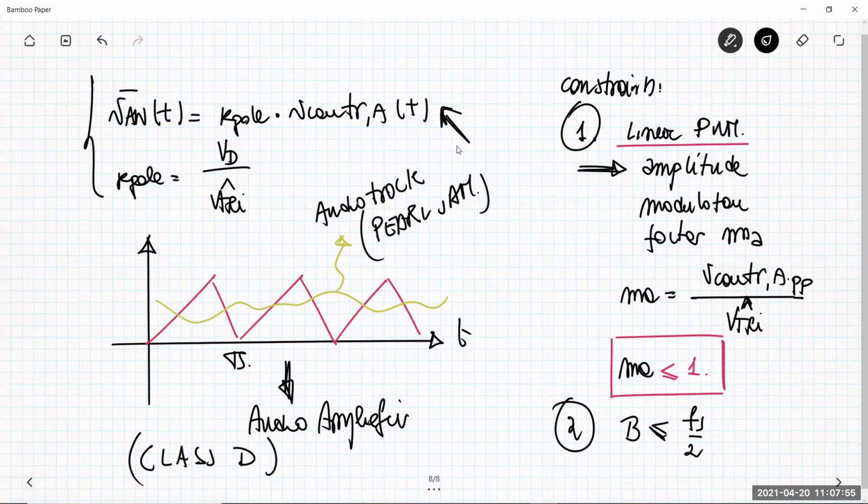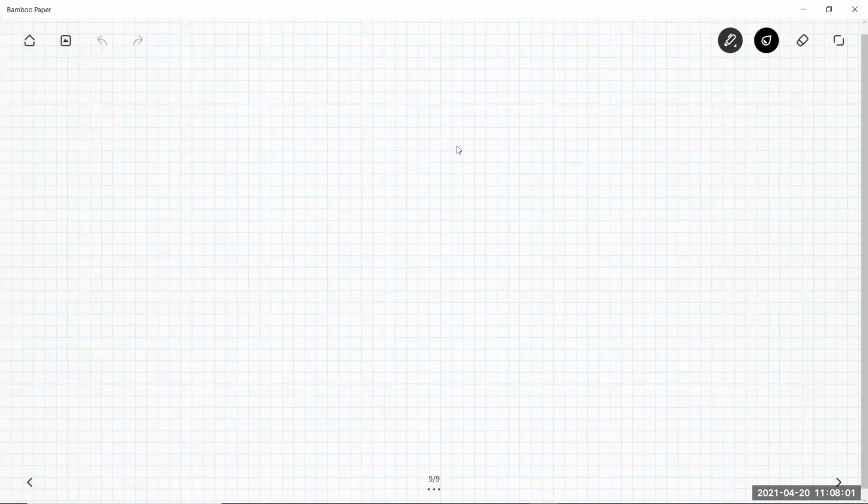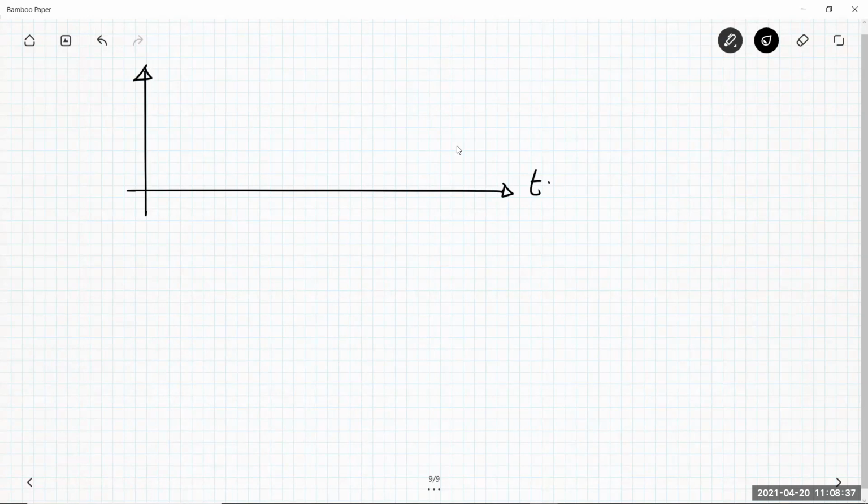Of course, this is not the topic of this course, because I want to just use this switching power pole for driving electromechanical actuators. So typically what happens in our driving applications is that the control signal is not whatever signal you can have in mind, but typically it is a DC quantity, as I did at the beginning of this lecture, for example, for driving a DC motor, or it can be a sine wave for AC motors, for example.